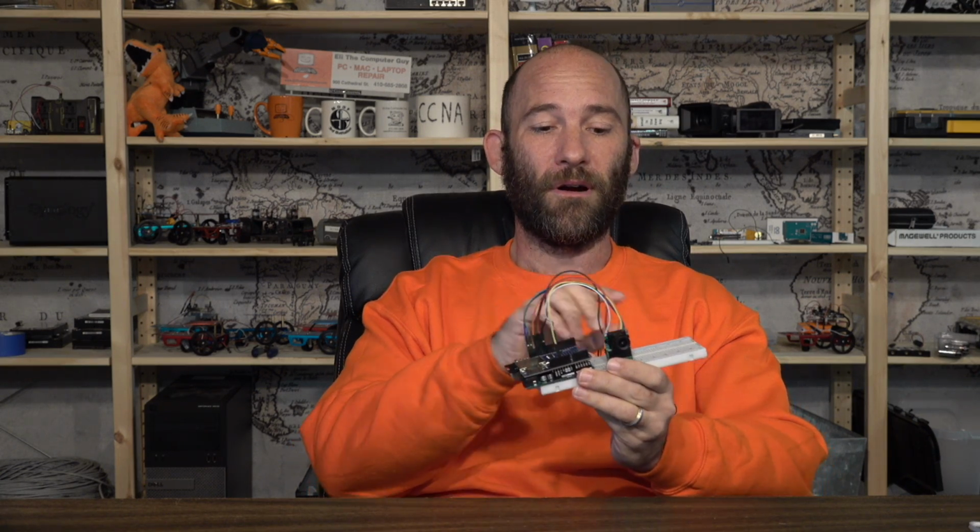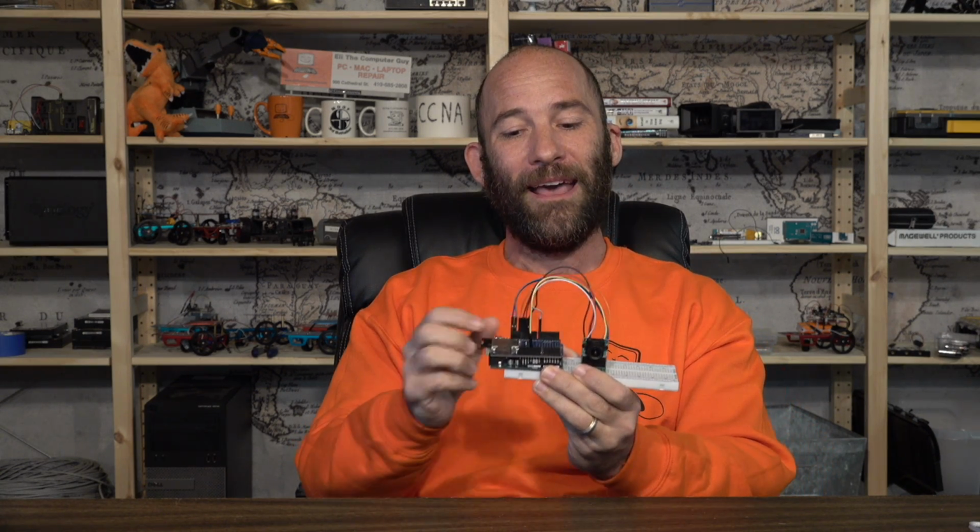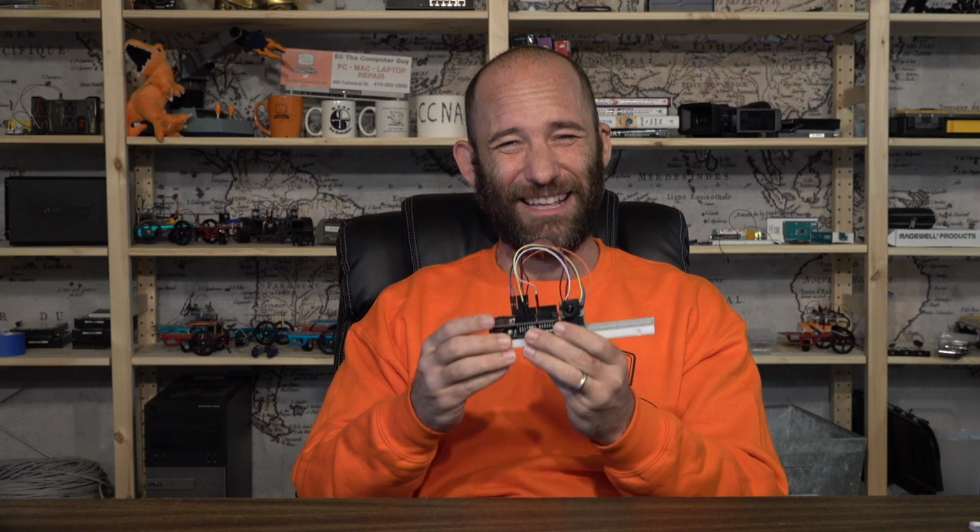Now, to be honest with you, using an Arduino in order to run an Arducam is a little bit of a push for the Arduino. The Arduino really doesn't have a lot of resources. It really doesn't have a lot of power. So you will run into some problems using an Arducam with an Arduino if you try to do things that are too sophisticated. So you need to think about whether it is really best for your project to use an Arduino, or should you be using a Raspberry Pi or something else? That's just one of those things you have to play around with and think about. But I think this is pretty cool.